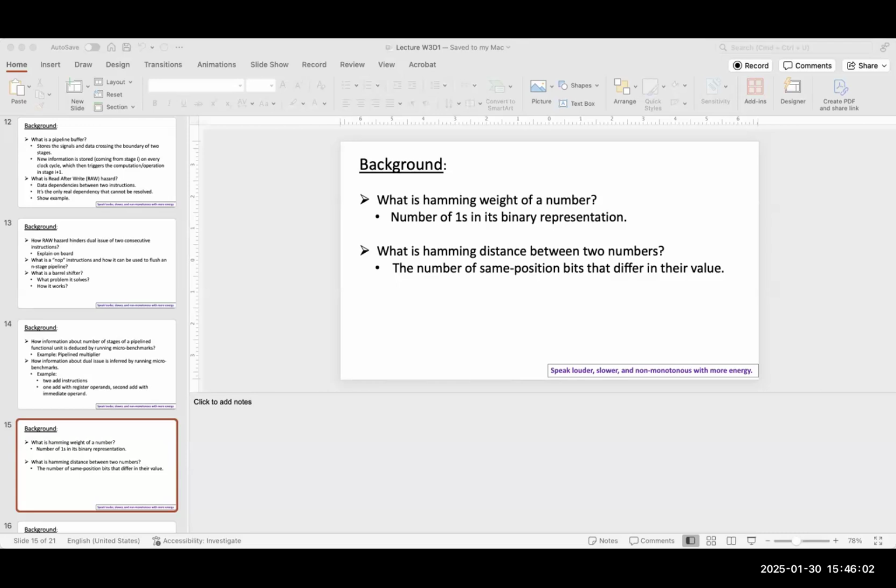Okay, any questions? It says they are not identical, but if there was ever a situation that they were identical, what would happen to the whole operation? Anyone who wants to answer her question? She's saying that in the paper, they found that the ALUs are not identical, in the sense that only one of them can perform the multiplier shift operation. The other cannot. Yes, there are two ALUs, but they are different in their capabilities. So her question is, if they are identical, what will be the implication? Wouldn't it be acting like a singular ALU at that point, since they're both doing the same operation?